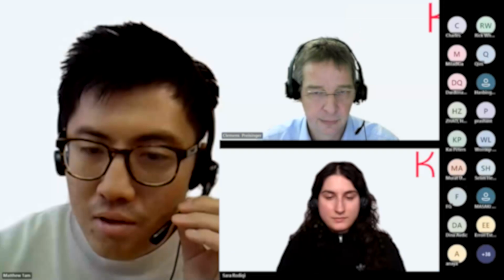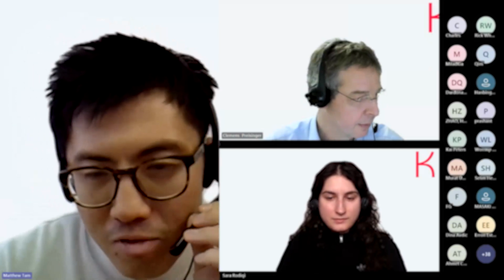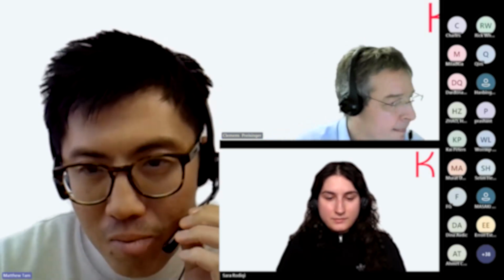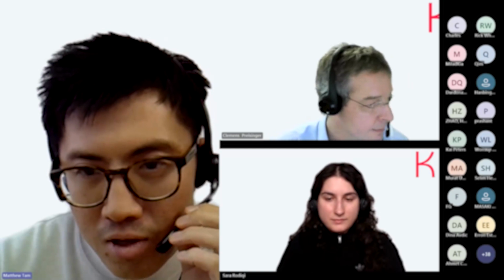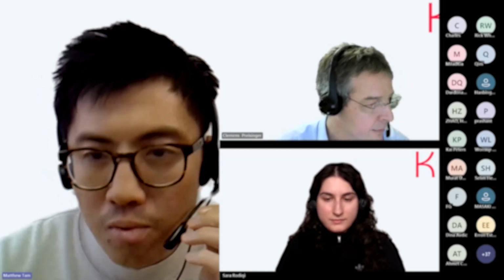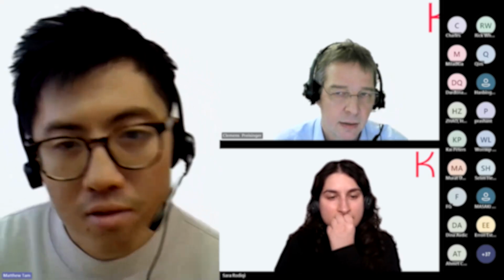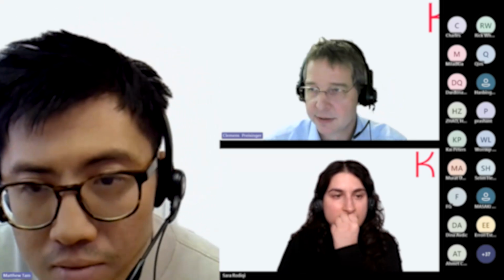Okay. There's quite a few questions. I'm not sure if we're going to be able to get through all of them, but I will try. I'm answering some in the chat, but maybe Clemens. One question was, does the automatic optimization component of sections, like optimized cross-section component, also include the verification of non-buckling of the bars? Yes, it does.